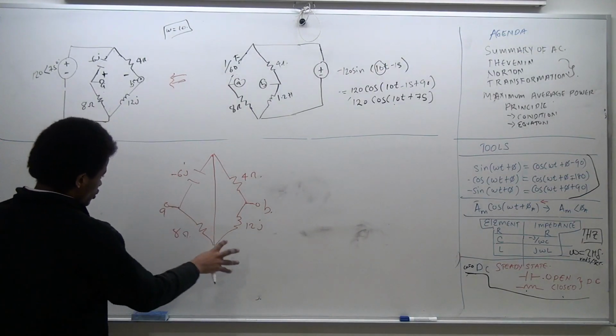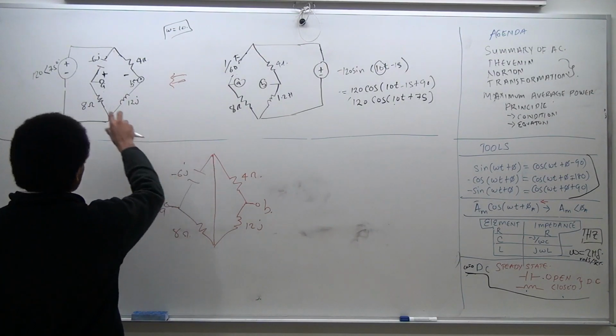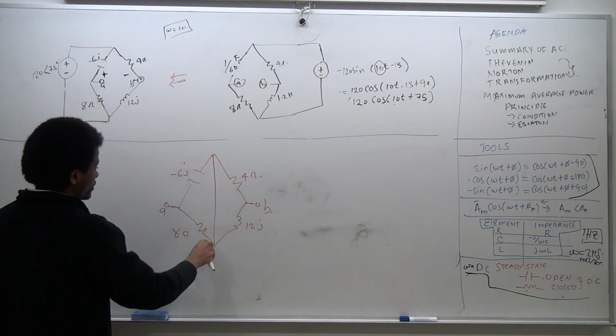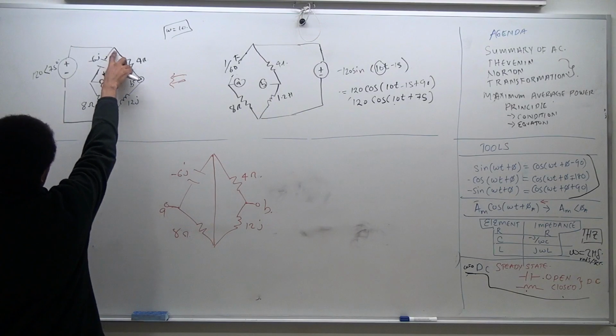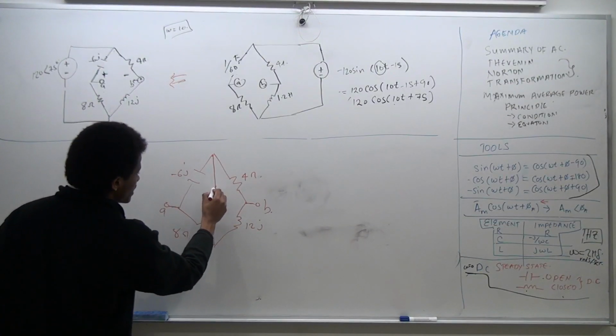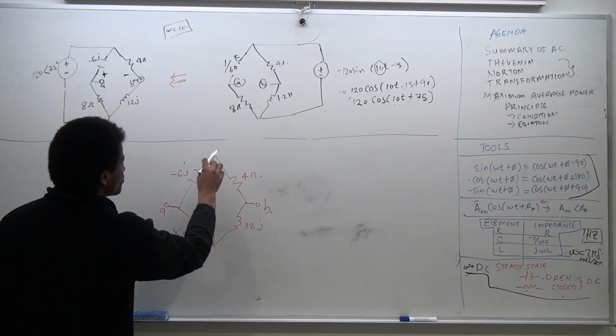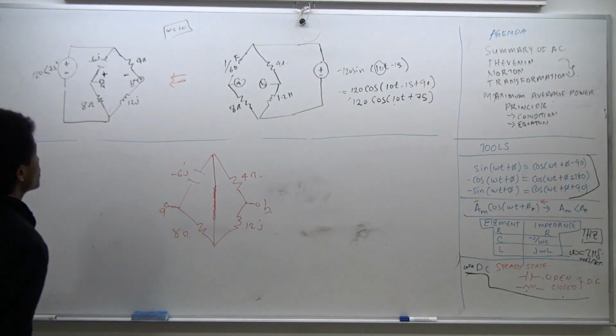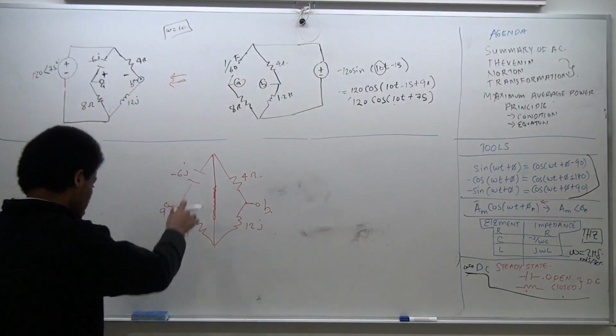So now we know there are no voltage sources, and we have substituted this voltage source with a wire that is actually a short, shorting this terminal, hence presented by this line. So this is the previous voltage source where it existed, and this wire actually exists now.